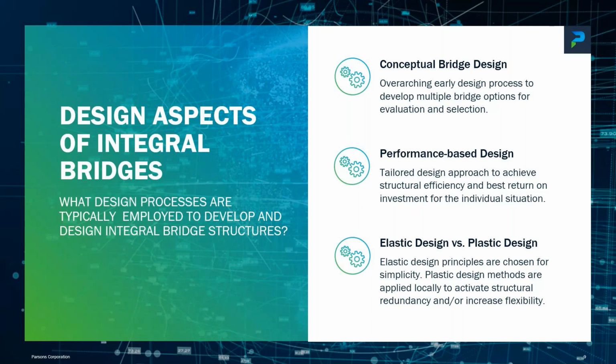So elastic design, you can just separate in linear elastic or non-linear elastic design. But I don't want to go too much into this. I want to just say, because it's, I think, not so clear to everybody, we're using elastic design for simplicity. And this is very easy to implement in models and to get more or less reasonable results. When it goes plastic, when you have non-linearity in the material, it becomes tricky because the sequence of building plastic hinges matters. And what we typically do, we don't do this on a global model because it gets too complicated. And I would not recommend complicated models.